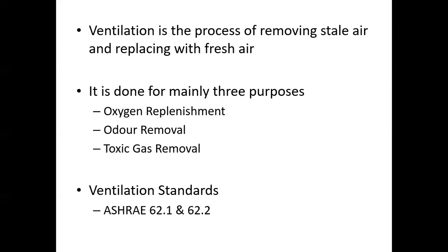So we will learn about the fresh air machine, which is the TFA, treated fresh air unit. Normally these TFAs are implemented to provide fresh air. Directly, it will supply the fresh air across the rooms at a temperature according to the comfort temperature. That's it. So how to size the duct? The velocity of the fresh air duct with fan should be around 1000 FPM.